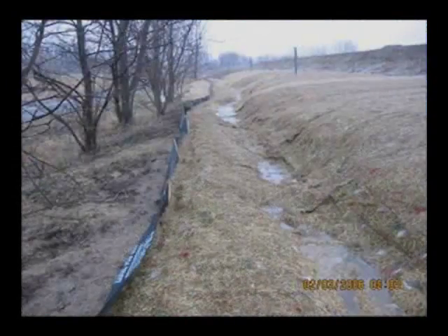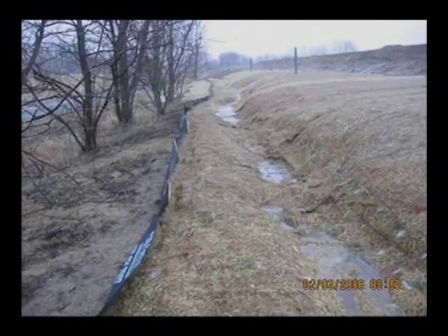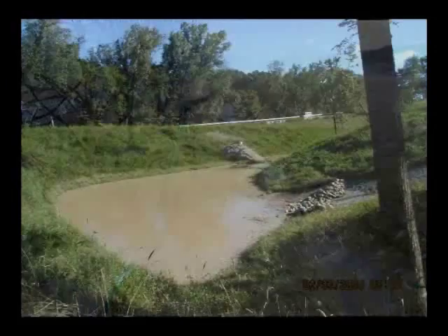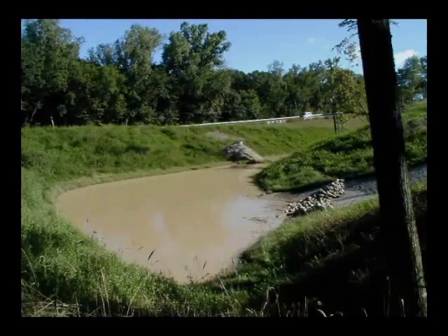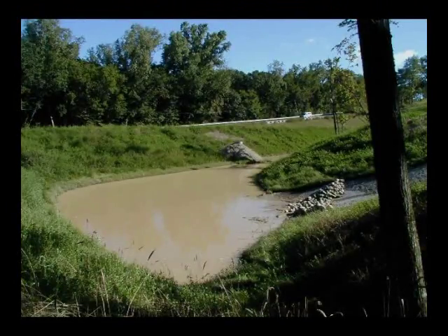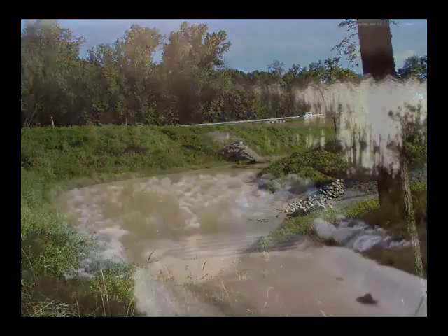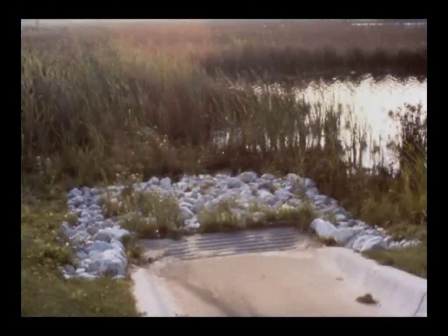Extreme care must be taken when constructing diversions, because it often results in converting overland sheet flow into concentrated flow. This may result in the erosion of the diversion channel or the channel outlet. The easiest way to dispose of diverted water is directly into a sediment basin or onto well-established vegetation. It may be appropriate to combine a grade stabilization structure or an energy dissipator at the outlet to safely discharge water from the diversion. If this is done, the inspector should ensure that the outlet remains stable.